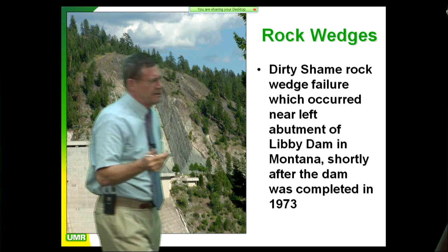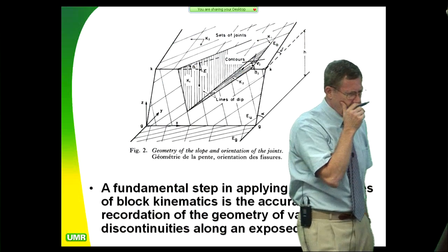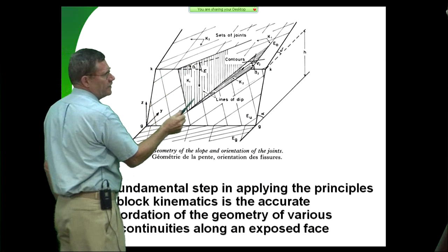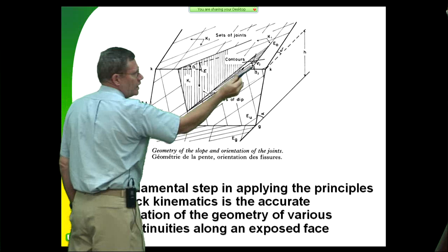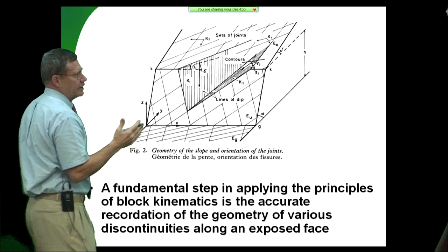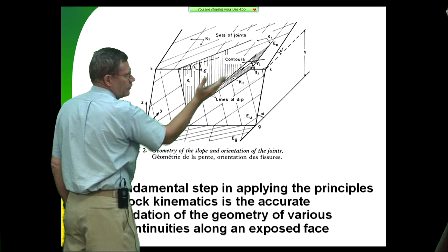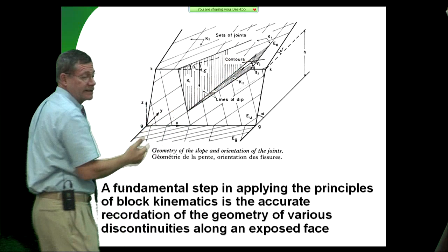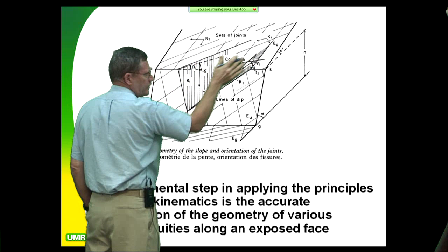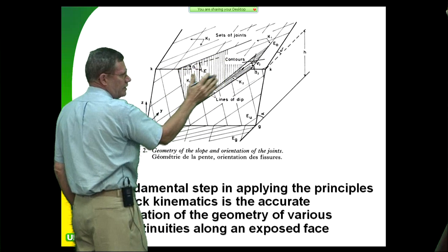And so the Corps of Engineers at that point did a lot of work on how to analyze wedge failures. Now, if we look in any of the books, this is about the simplest kind of wedge failure you'll see, like the one I just showed you, where you have one plane here, you have another plane. They're almost never symmetric, and usually you're sliding more on an apparent dip on one of the planes than another one. Sometimes you come down right along the intersection like the one I just showed you, but that's pretty rare. Generally, they look something like this. And you might get a smaller one up here first, and after it comes out, then you get a little bit bigger one. And after that one comes out, you even get a larger one below that.